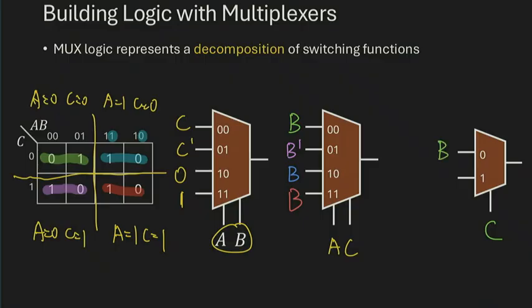And when C equals 1, the output is 1 when AB equals 0, 0, or 1, 1. And that is the XNOR function between A and B. So you have to put down a function of A XNOR B at the 1 input. If this is the only mux you have, you probably need to use some gates to implement this XNOR function. Or if you have another mux, you can implement the XNOR function using another multiplexer.